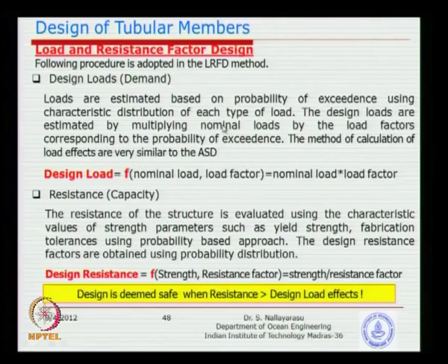You take the maximum load that may occur during the design life, but that maximum you only guess. You do not know whether realistically that is the maximum or there is another maximum which you do not know. So basically in this method of LRFD, you try to assess scientifically using probability distributions and find out what could potentially be the maximum, and then arrive at the risk of exceedance of a particular value.